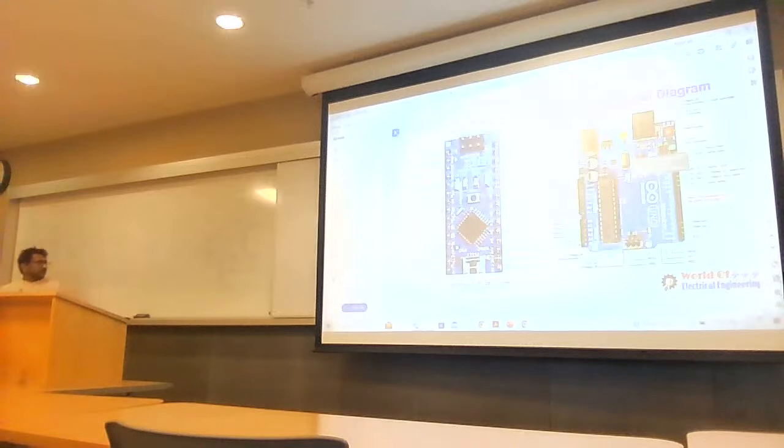We have one more oscillator, which is the VCO, voltage controlled oscillator. It means that we can control its frequency using voltage. If you increase the voltage, you can get a huge frequency from here, at the gigahertz level. But the VCO is not stable. Even a slight difference in the input voltage will change the output frequency of the VCO.